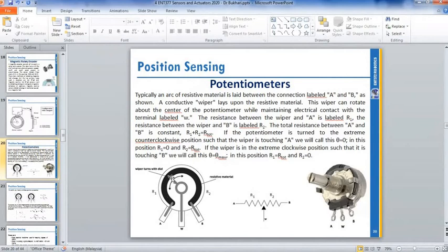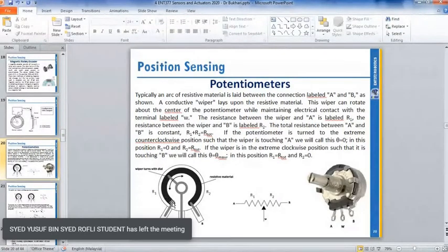So this we call a wiper that changing your value of resistor. This is common, W or common. So if your wiper is turned to the left until contact A terminal, so your resistor between A and W is 0 ohm. 0 ohm because you don't have resistor value because your wiper already turned maximum until near to the pin A. So your resistor will be 0.